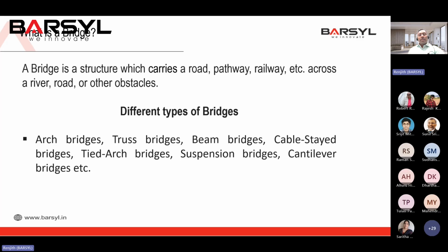In simply supported bridges, the major issue is the expansion gap, and the ease of movement. You might have noticed unevenness while crossing a road bridge. In order to avoid that, we can have continuous bridges so that expansion gaps will not be there. But that needs to be designed for the additional forces due to temperature and so on.